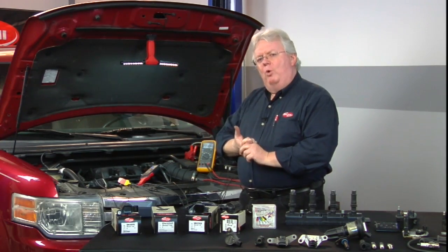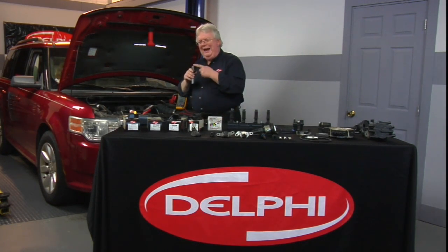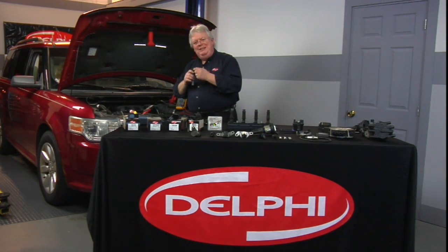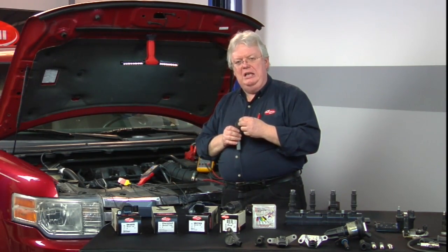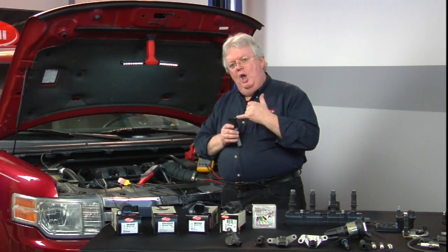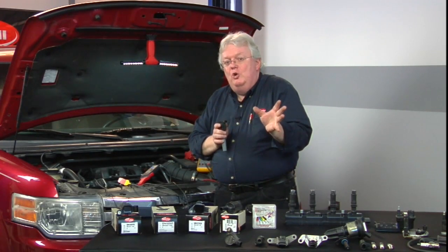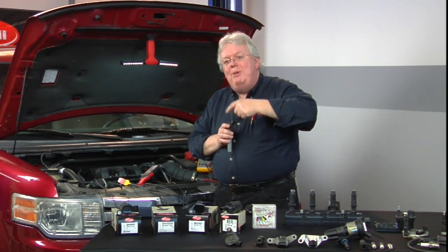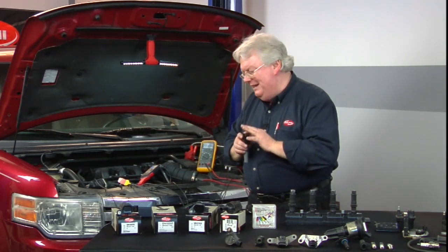What we've got is 4 channels connected today on this coil-on-plug. So we've got the 2 wires I described, your power from the ignition and the ground supplied by the computer. We're going to back probe both of those. We'll see what the ignition does when we first turn the key on, and then we'll also see what the negative side does. Key on, engine stopped, it shouldn't do anything, no ground, so we should see power on both sides, OCV, open circuit voltage, applied to that primary winding.